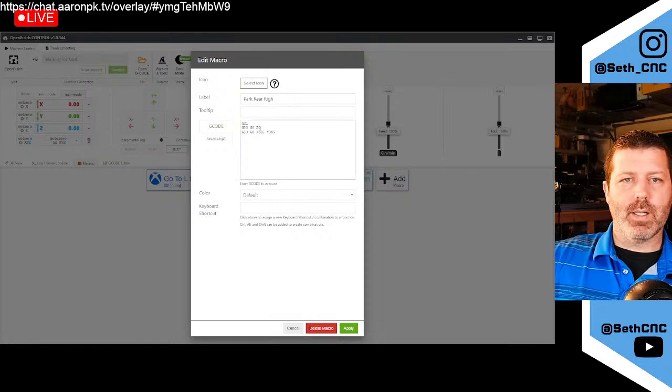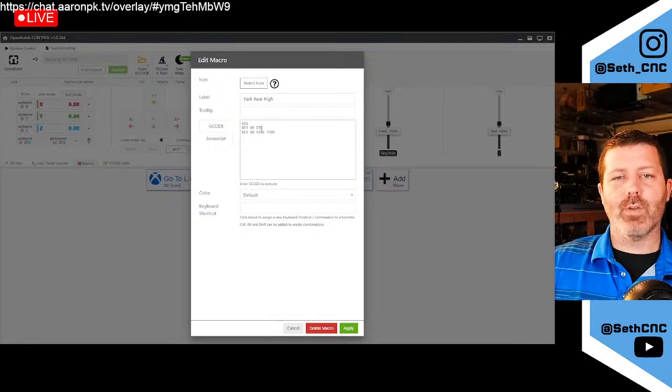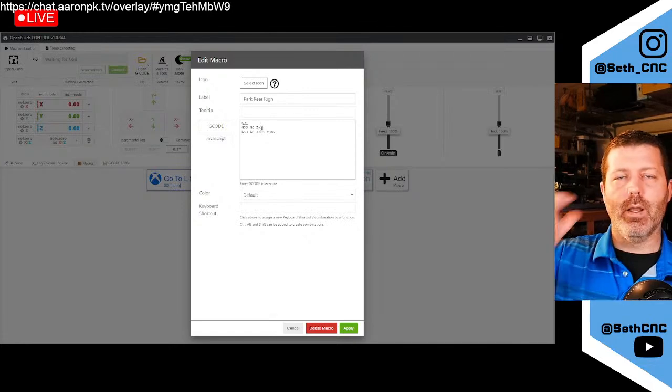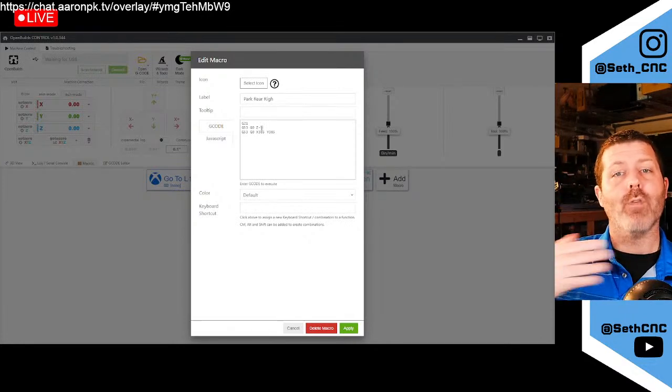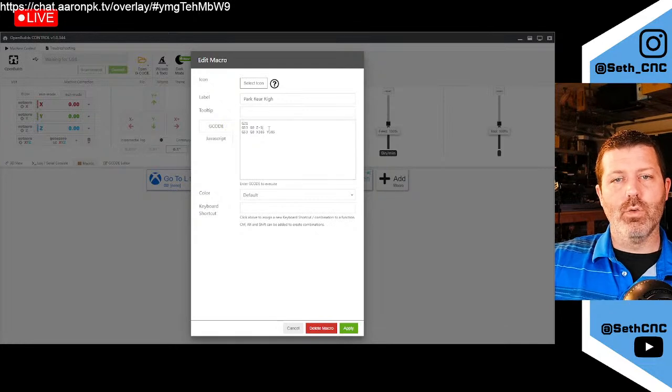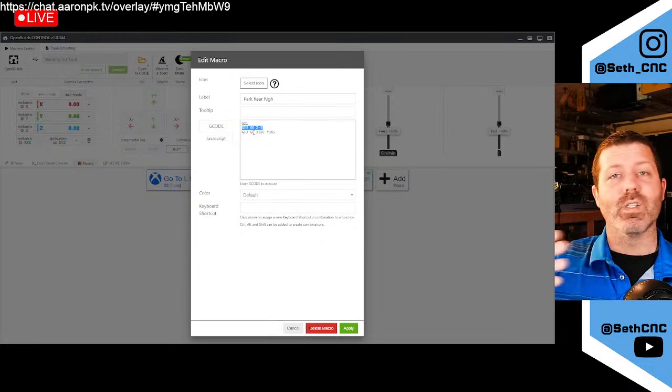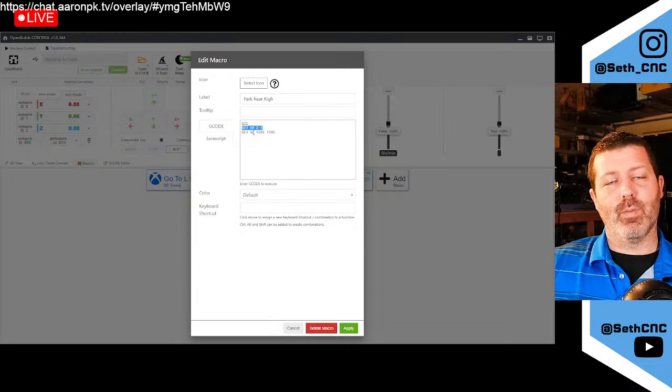Yeah, and the other thing is setting it to Z0 will actually activate the home switch. So this actually needs to be a little bit less than that. So we'll do like -5 or -10, that much down below the home switch. If you don't want the Z to move at all after the carve and just XY for parking, you could delete this line out, and then you've got just that absolute diagonal jog coordinates from wherever it's sitting on the machine to that coordinate, 385 by 385.